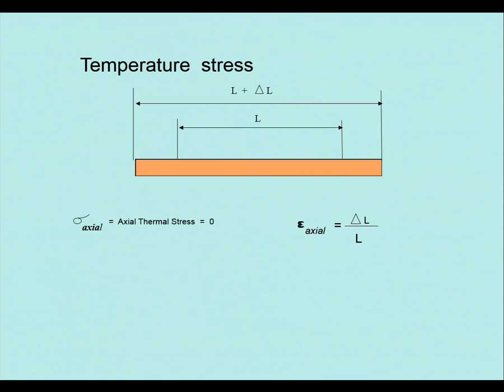But it can't be correct. There's no material properties for that. One's bringing about the extension. So what it's saying is I've got a stress with no strain and strain with no stress, and that can't be. So the only way you can get a stress in this bar, pardon? We need to constrain it from both sides. Before you expand it. Yeah. Or similarly and equally.